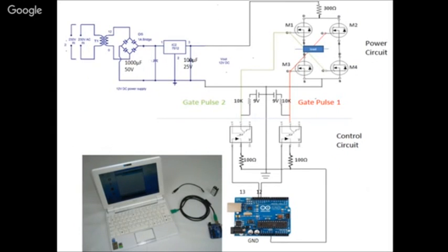So this is one of the small real-time hardware projects which was done here. That was an inverter. So an inverter converts DC to AC. You had a rectifier. This was the power circuit which operates at 230 volts, and this was a controller circuit which operates at lower voltage. Here around 9 volts was the voltage at which this was operating. This is the microcontroller. It will just generate firing pulses for these thyristors to turn on.